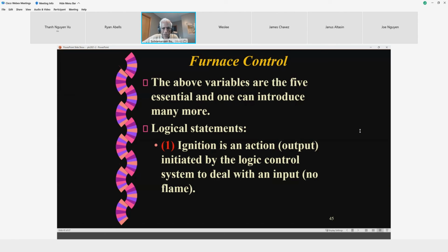Okay, I've got only 2 minutes left. So the next step is to put logical statements for each of the outputs, as to what the conditions required are. And then this problem is also going to go through the backward route of constructing the hardware and transferring it to a logic network diagram without going through the truth table. You can also go through the truth table, and I will show you the truth table after I finish this. Any questions?